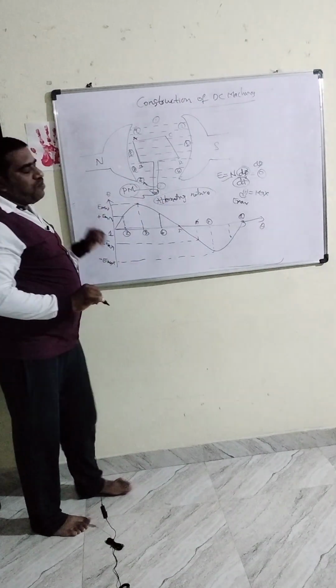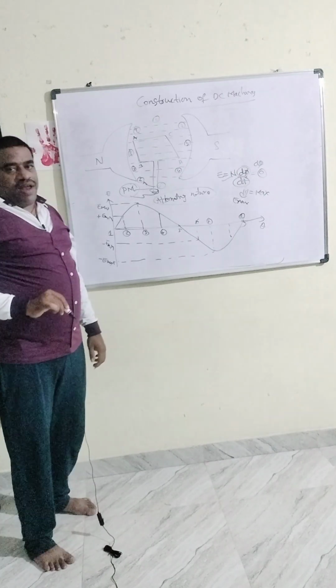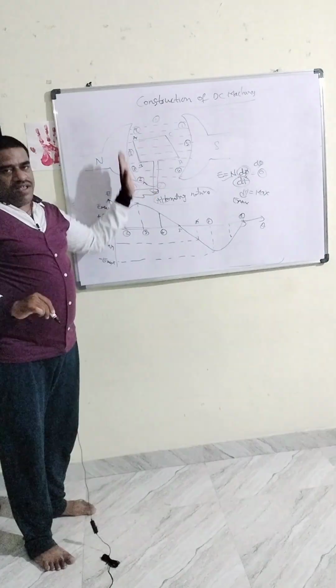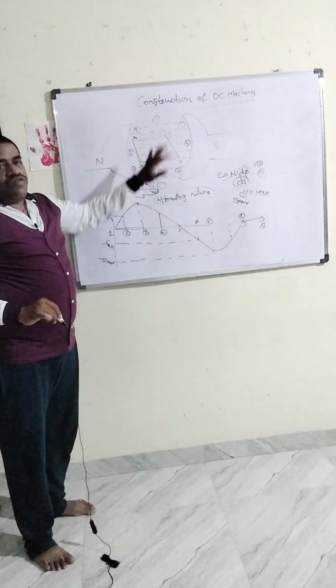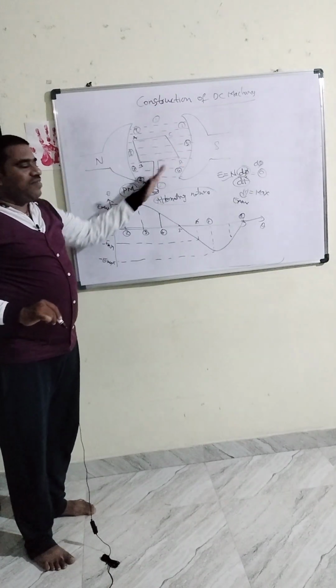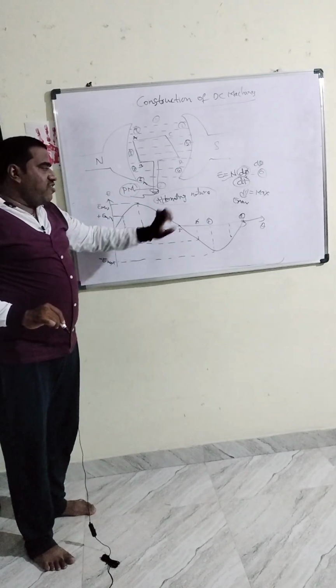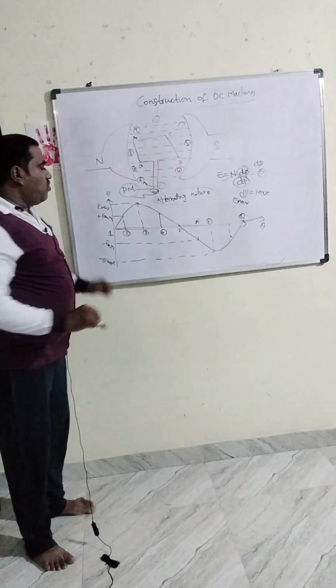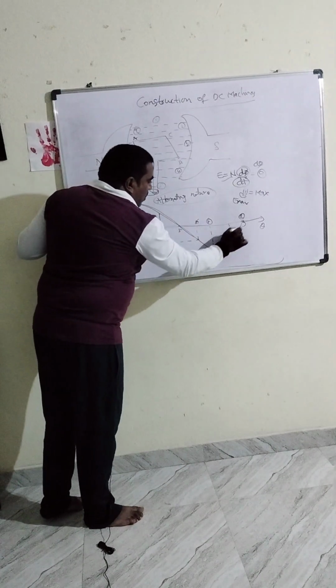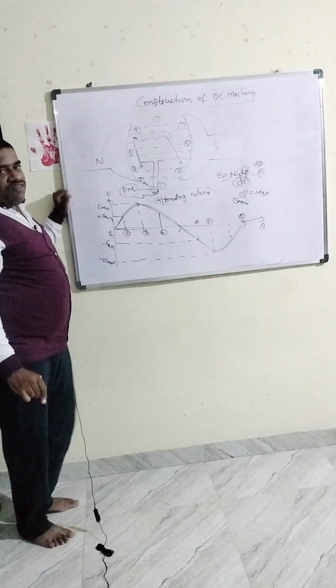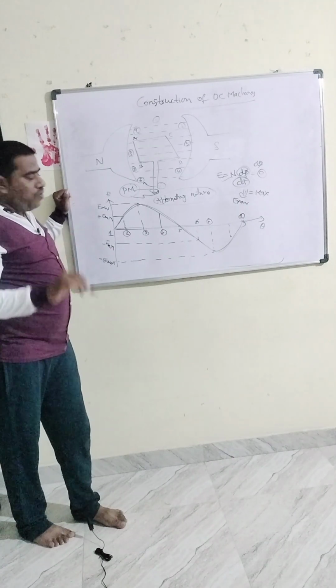A mechanical prime mover, a turbine, is what we use to rotate the armature here. So the field is stationary and the conductor is the rotating member. That's why we call this dynamically induced EMF, and the nature will be alternating. So the alternating EMF is converted to DC by using a mechanical rectifier, the commutator, to convert AC to DC here.